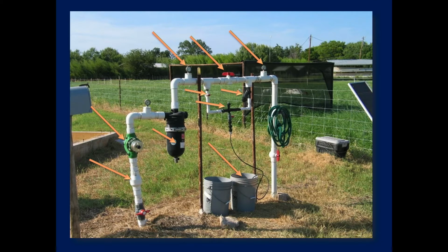So anyway, this is a pressure reducer. A lot of times, remember I said these operate under low pressure, so 10 to 12 psi. Normally from a well or city water, you may have 70, 80 psi typically coming through it. So you typically need to reduce it, and that's what this is. This is a variable rate pressure reducer, so you can actually change it based on whatever's coming into it.